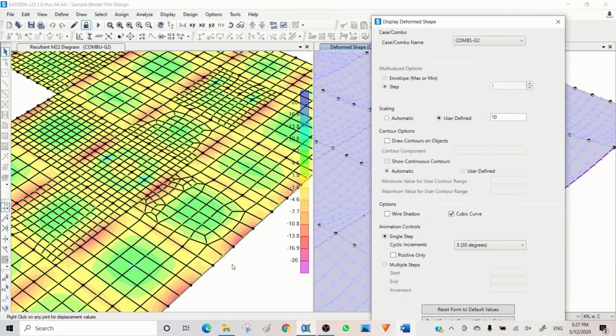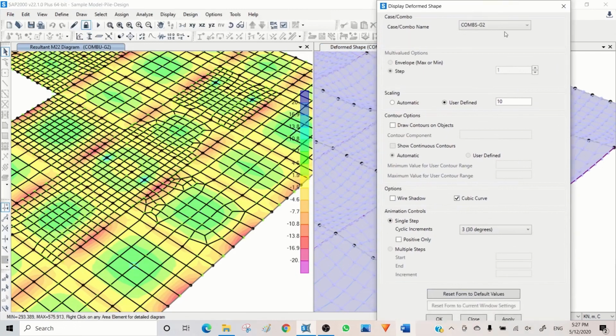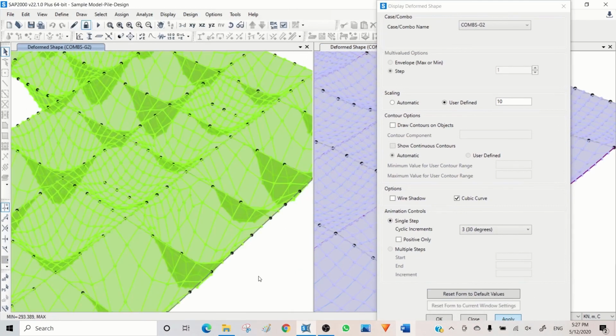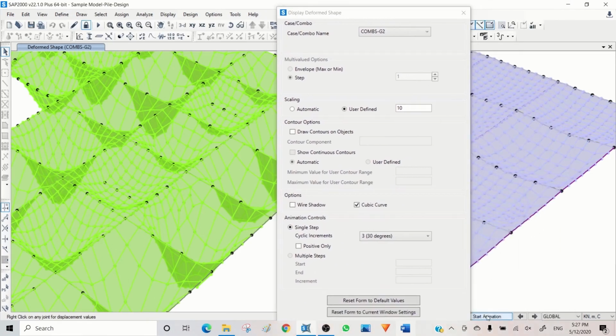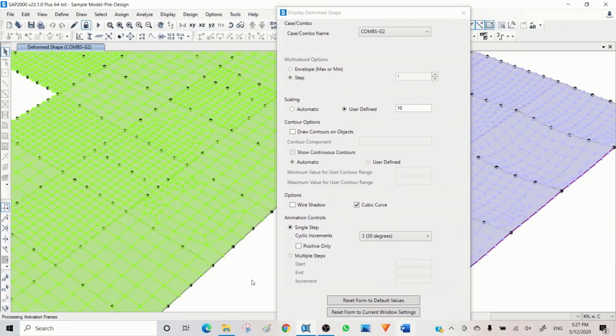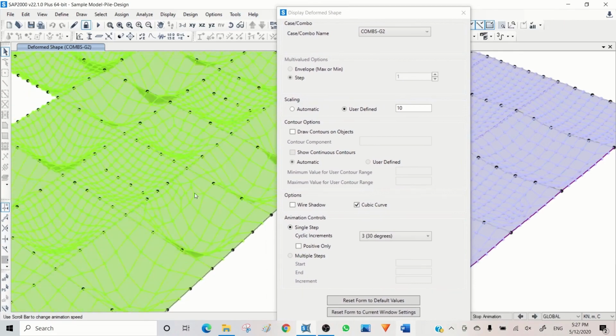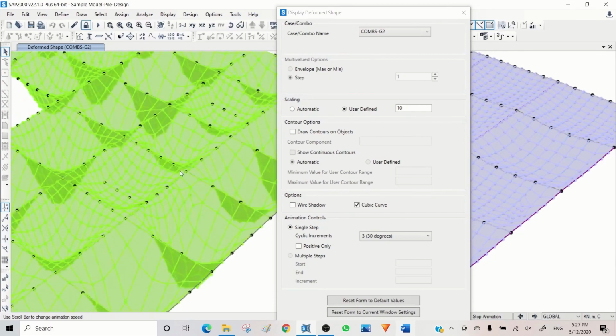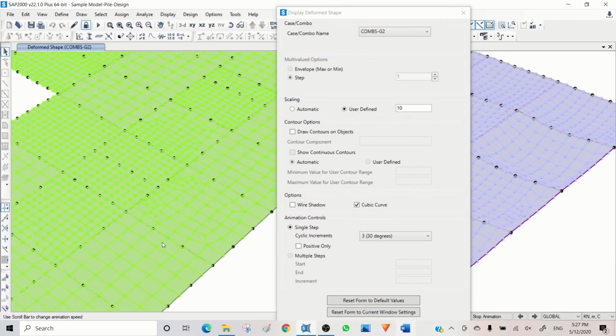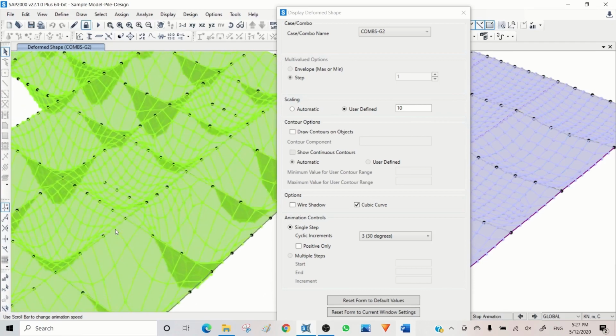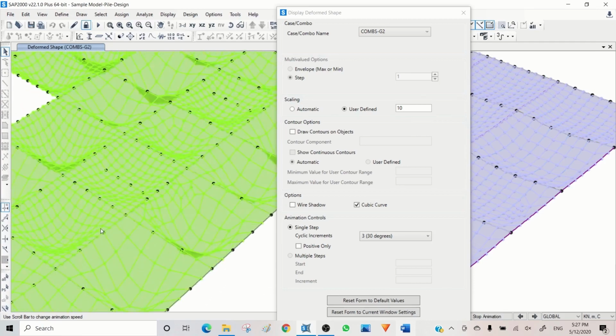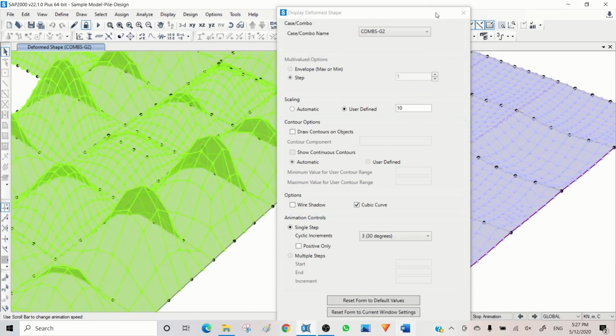See what's happening here. Yeah, I'm not surprised of such a big deflection on the slab because the stiffness is very low. So if I go to animation, regardless of significant move in a slab, you see the beams are properly connected and they are moving. The movement is not considerable and is not very visible because currently a slab is moving very hard.